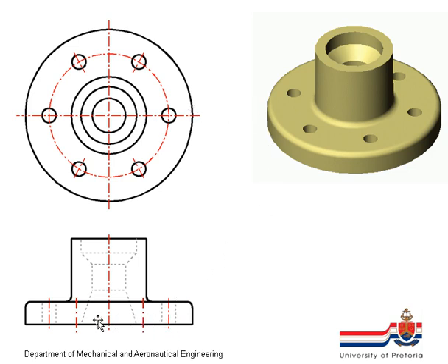Center lines are always shown for all cylindrical features. Remember previously I said hidden detail doesn't need to be shown always, so that's why we don't show the hidden detail for there and there.